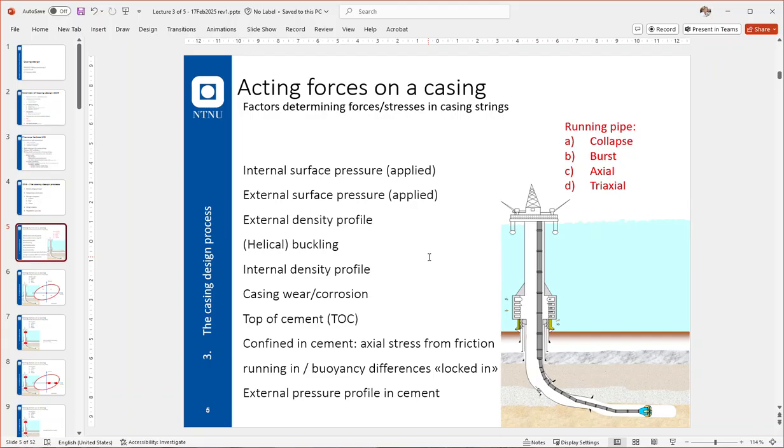Once it's in the middle phase, and that starts basically 1 hour after pumping, when the cement has been in place for 1 hour, we have pumped it, we have stopped the pumping, and it is in the annulus where it's supposed to be, or where it has to end up because of, call it operational factors, meaning you had maybe some problems and that was not exactly how you planned it, but this is how it has to be for all matters.